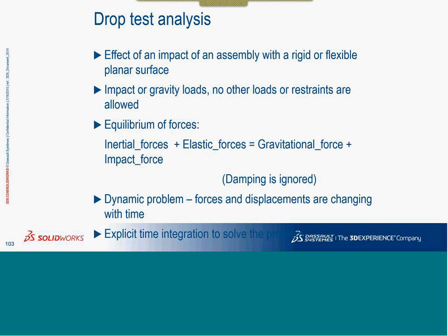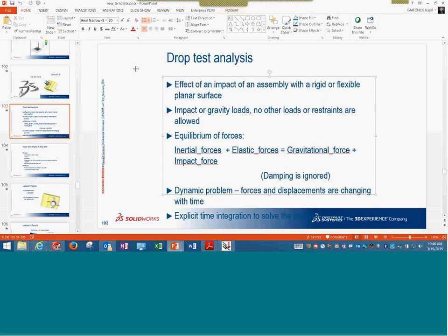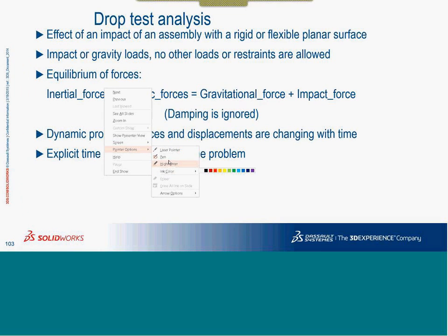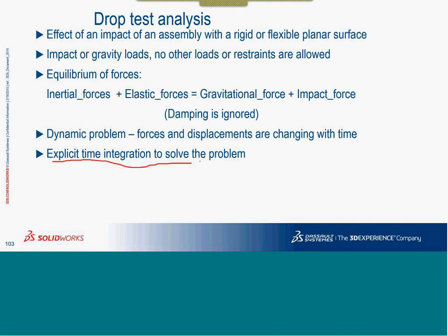Okay. First and foremost, remember, this is the only module which is actually using explicit time integration to solve the problem. So this is not an implicit solver. This is an explicit solver. Typically, explicit solvers are stronger in cases of large deflection, I would say. They involve large changes in the locations or movements of the body. This can also cause a large amount of stress in each of the local elements. Okay, this is how it is.